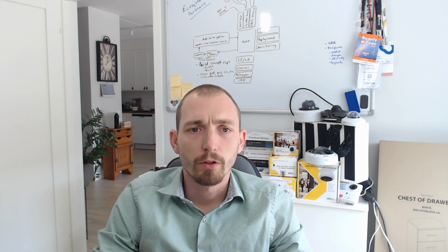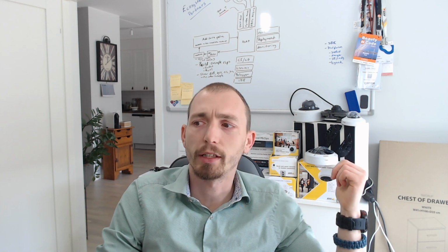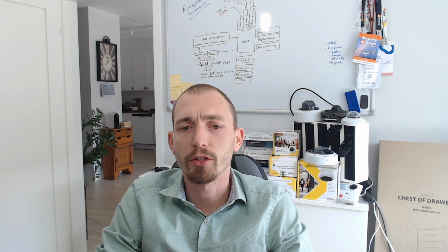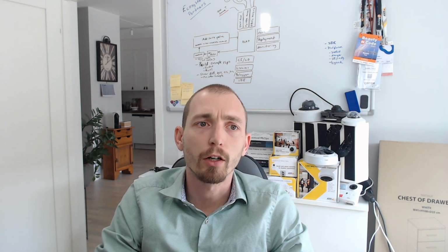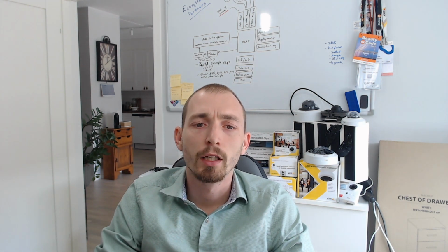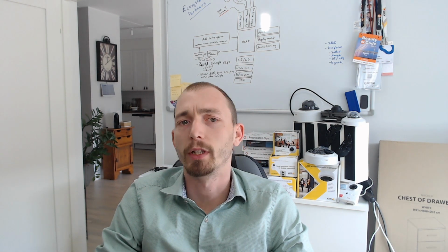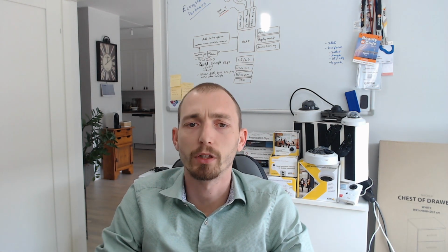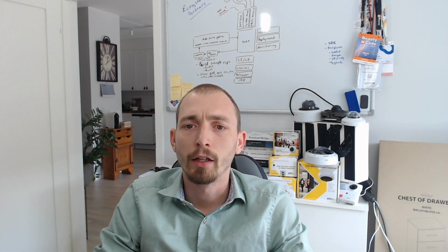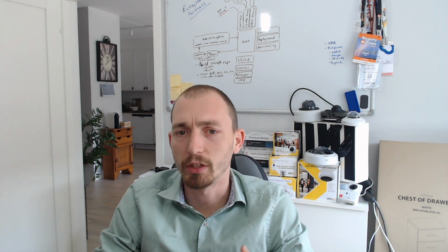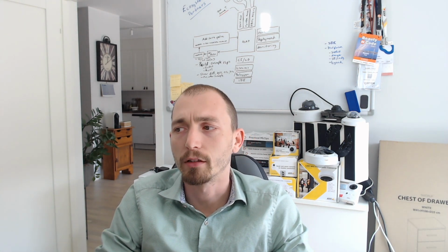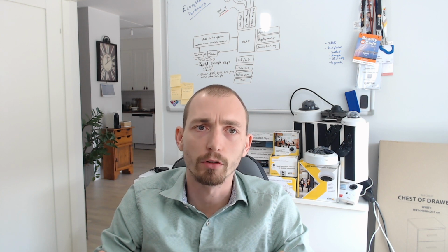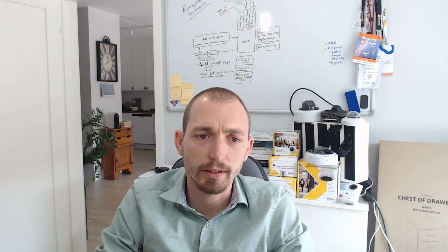Developing applications for AXIS cameras like the ones you see here behind me is a bit more complex than developing applications for your local PC environment or cloud environment, mostly because it is more complex to interact with a device. There is a bigger variety between different devices, and you need to SSH into the device which is running headless and so forth. So one of the things that we have been doing here at FixedIT Consulting is to create tools that make it easier to work with AXIS cameras.